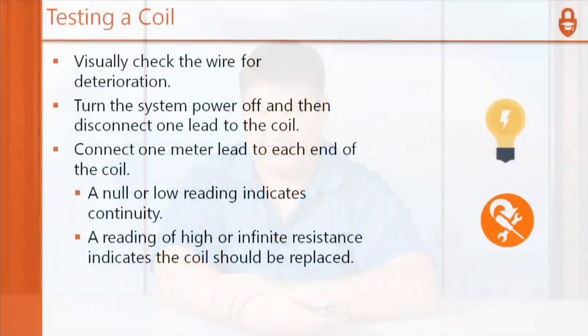So, testing a coil: visually check the wire for deterioration. If there's pitting, corrosion, anything like that, it won't work properly. Test the system power on and off. Turn the system power off and then disconnect one lead to the coil.